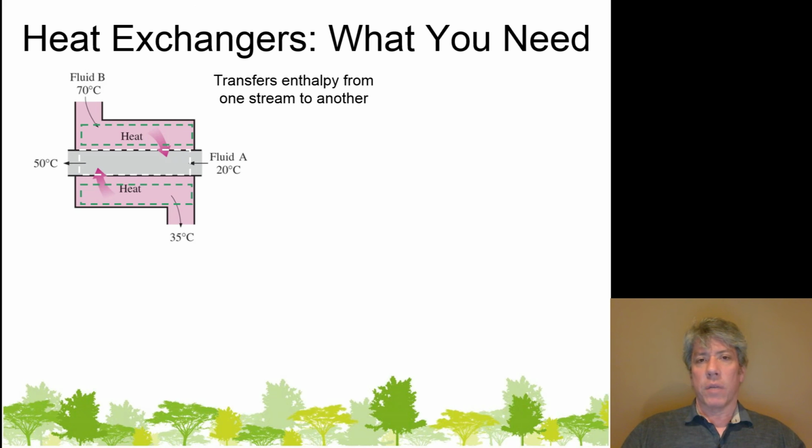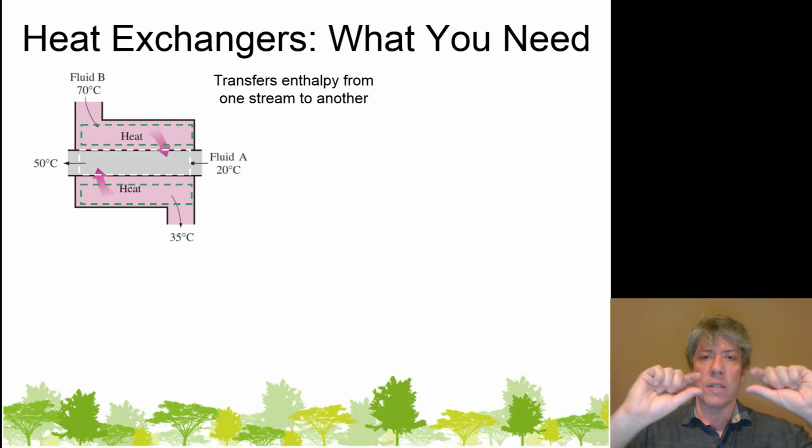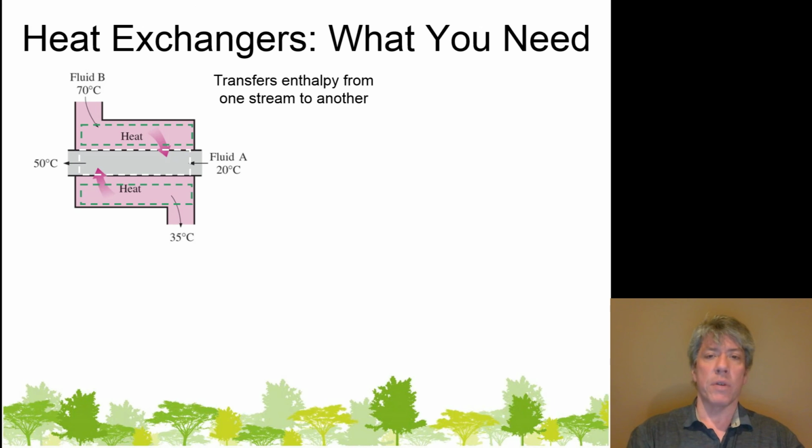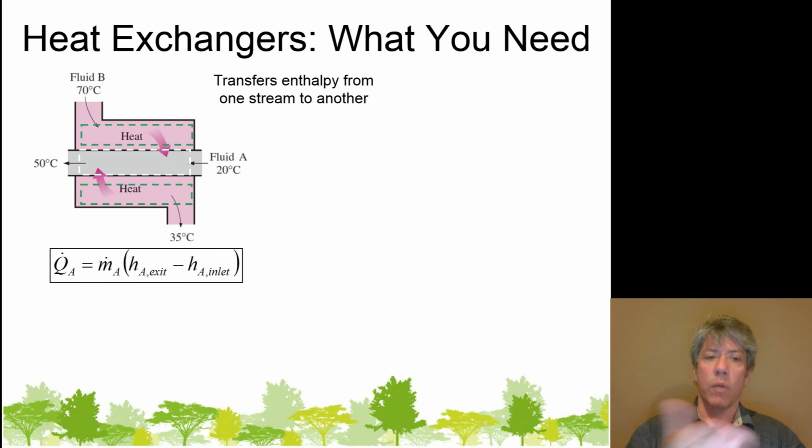Now, you might have looked at what I just showed you and said, wait a second, this doesn't seem fair. You're just confusing us for fun because it's called a heat exchanger and yet there was no heat transfer in that last equation. Well, let me draw two different systems that are equivalent to that last system. Let me put a system boundary with this white rectangle around fluid A, and imagine that this is simply a double pipe heat exchanger, so the green system is actually revolved around the pipe that fluid A flows through. Okay, in that case you can see that there's heat crossing the system boundary, and I don't get to eliminate the heat transfer term from the equation, but I do still get to eliminate work, kinetic and potential energies, and what I will be left with is this.